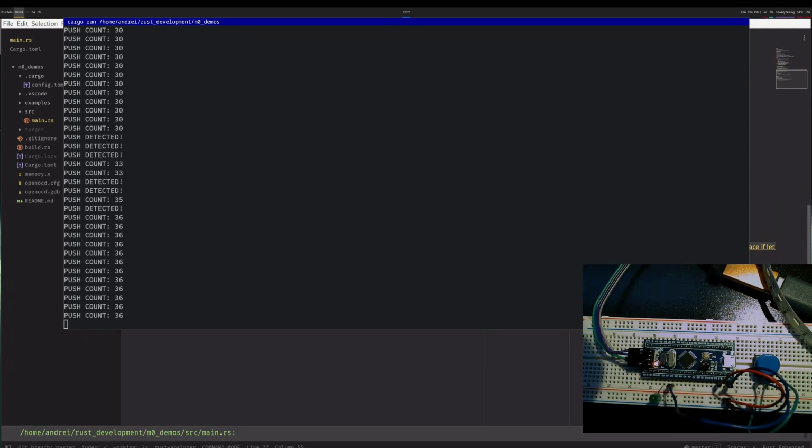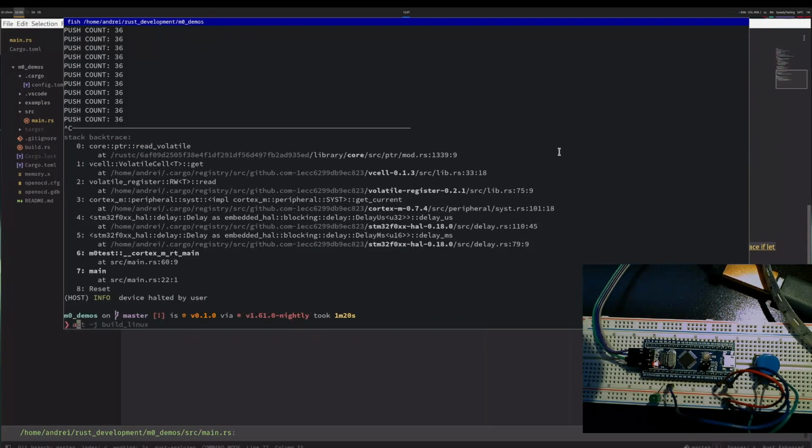You have to handle this in software. It's called debouncing, and the general rule is that physically I am not able to push the button more than, let's say, once every millisecond or once every 50 milliseconds or something like that. So you put a timer or a timeout in software that says once you detect a push, do not consider any value changes within the next X milliseconds as a new push, and that should work fine. I won't be implementing this in this example, but this is what you would do if you were implementing, let's say, some sort of game controller or a keyboard or anything that really cares about how many times you press a button. It would be really unfortunate if I press an A here and 5 A's show up on my keyboard.